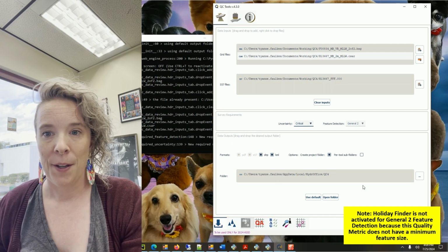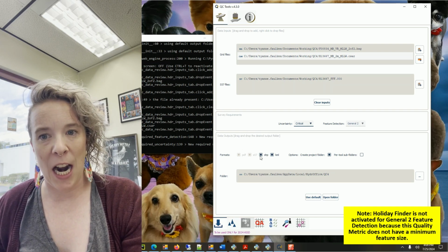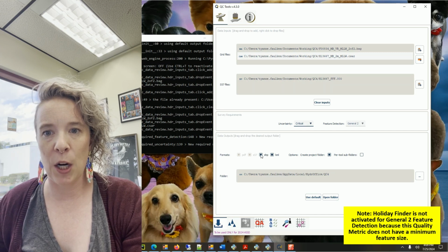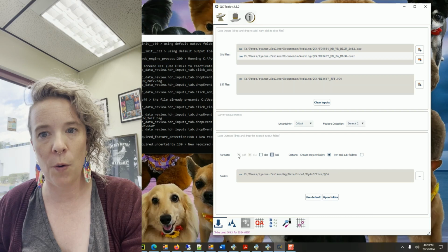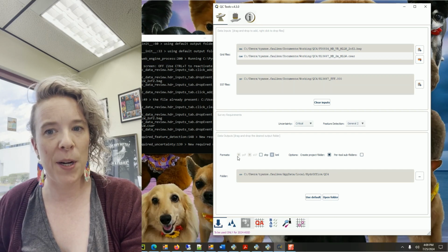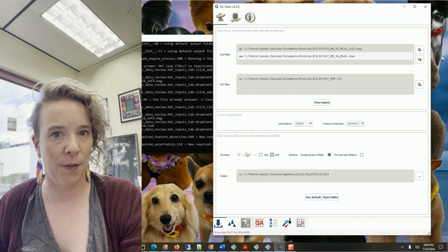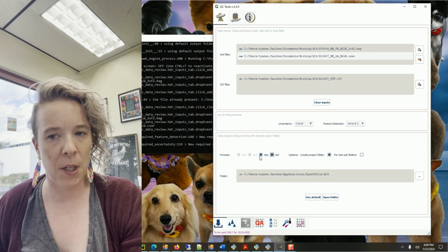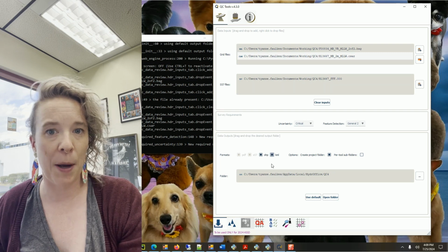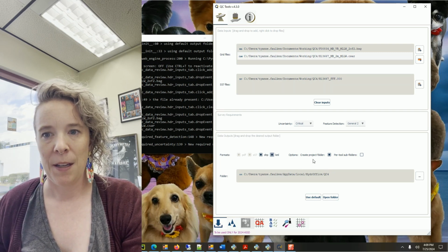The next box down here is the different types of data outputs. So here you can decide if you would like a shapefile or a KML, or you can turn them off. We always produce, depending on the tool, a PDF and an S-57. That's automatic, you can't turn those off. But you can select a shapefile or KML depending if you're using a GIS that accepts those things.